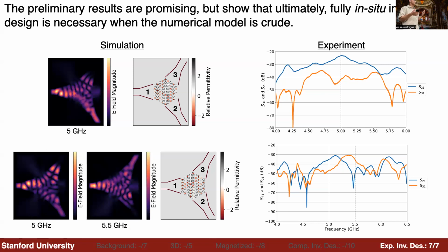And then likewise for the demultiplexer, you see maximal transmission in the right frequency range, and you're still getting on the order of 15 dB isolation. In fact, even S21 has almost like a band gap here. But there are a couple of things to point out here.